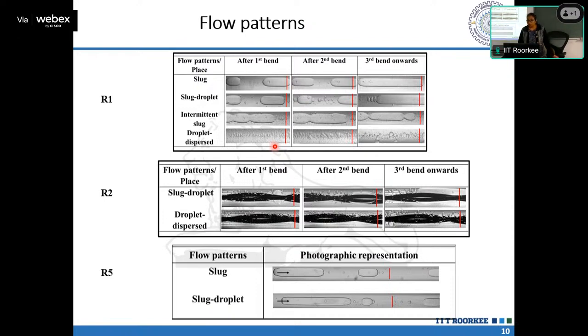We are giving the input of volumetric flow rate, and you can correlate it with the molar flow rate. Of course, you know the molecular weight and the density, so you can calculate the molar flow rate. By influencing the flow rate, you are influencing the specific area of contact, and the residence time also, right?